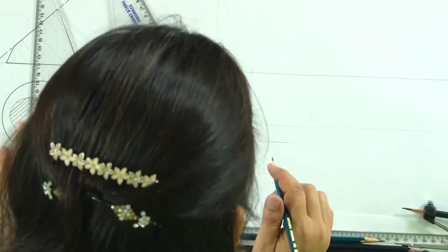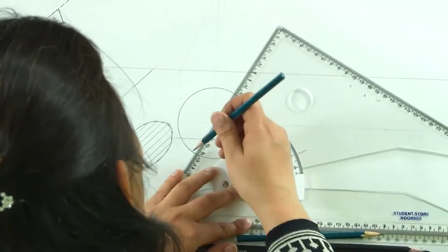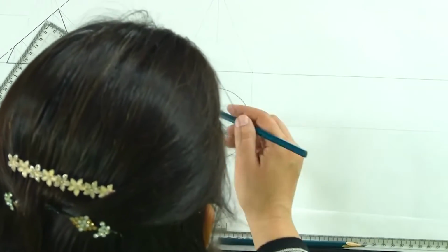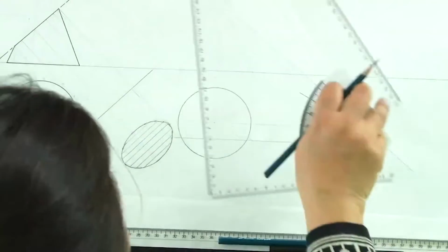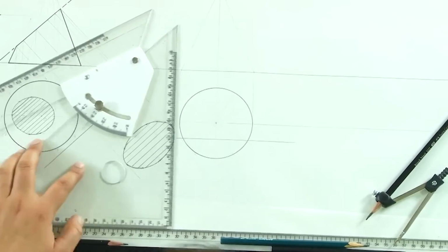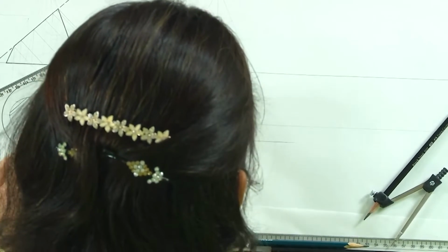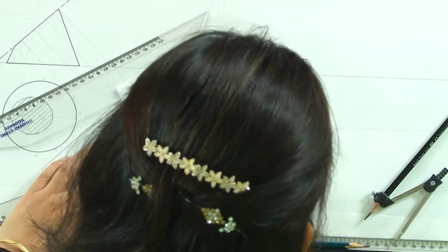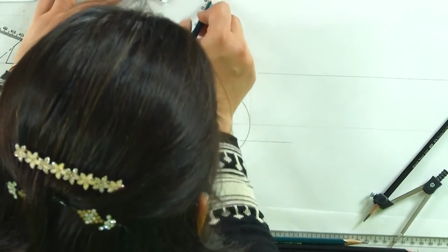So for this again we will divide it into, let us see whether we can get the solution by dividing it into 12 equal parts or not. Because all the times we do not get the solution to the conic sections by drawing generators. Sometimes we have to use some other methods, but let us see if we can get the solutions here. Now what happens here? If we look at it from top, so we will first draw the generators in the elevation as well. And we will connect the generators. So these are the generators.